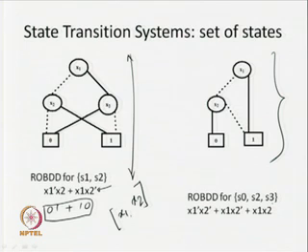With similar encoding, we are going to look for the subset which consists of states S0, S2 and S3. Since we know the binary encoding, we can write down the Boolean expression for this particular subset. Once we have this Boolean expression, you can always construct the ROBDD for it, and if you construct it, you are going to get this particular ROBDD. And the variable ordering we are choosing is X1,